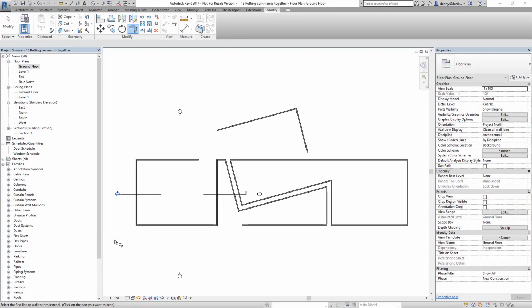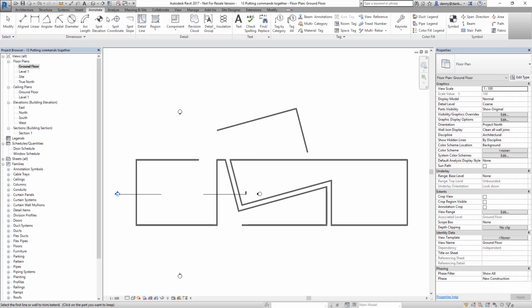So we've started to draw our little floor plan, but what we need to do is start giving dimensions and controlling how wide objects are. The way that you need to control all your walls and all your objects inside of Revit is with the dimensions. So I'm going to hit Escape, DI for dimension, or you can go into your Annotate tab and find dimension through there.